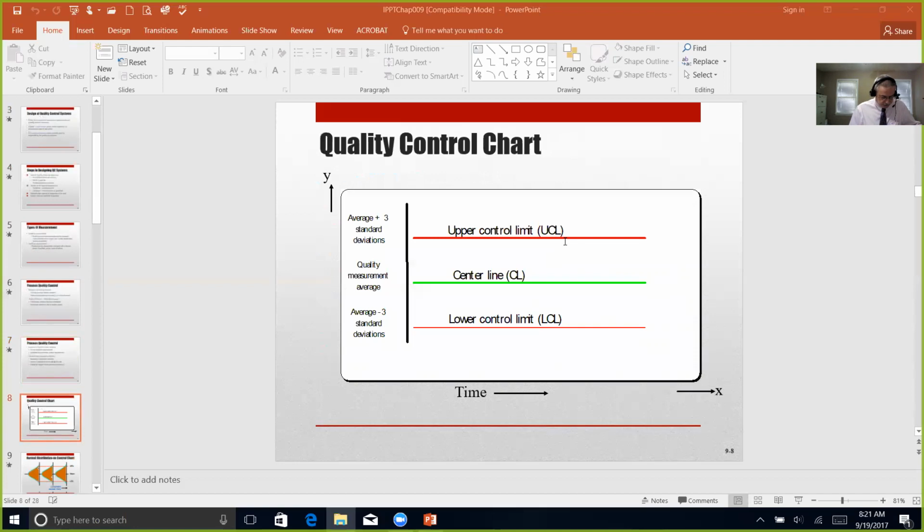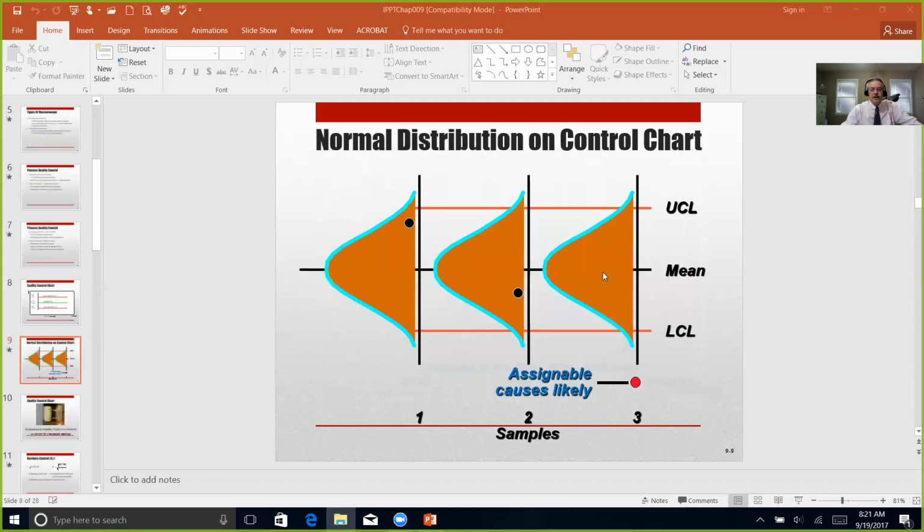So that is a way that we can use quality control charts to help us determine if this is where we want to be, what's an acceptable out of tolerance upper and lower. And when we get either upper or lower, like we have here, understanding why, what caused this, assign those causes, then go identify what caused that, then correct those causes so that we can get back within our upper and lower limit.